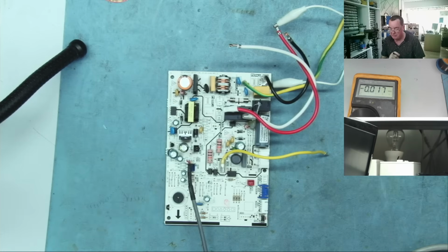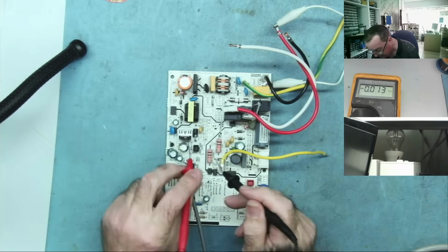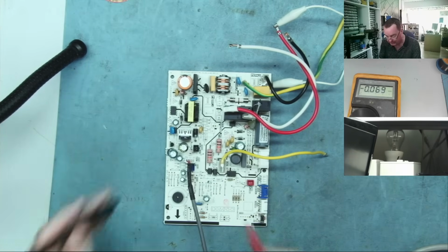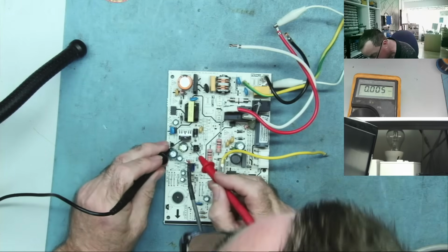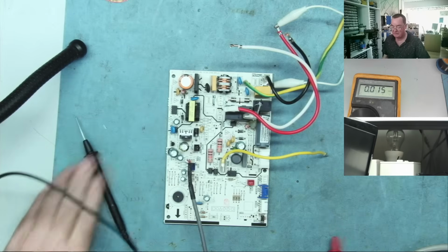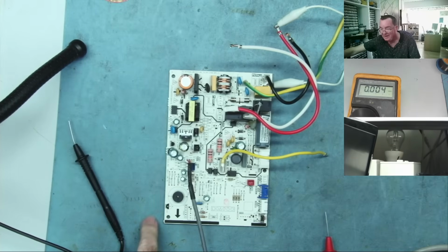Then, I know this is a 7805. So if I measure between the centre pin and the right hand pin, that's the output of the regulator. And if I see 5 volts here to here, I know the 5 volts is there. And if that's there, everything else is probably okay on the power supply. So let's switch this on and let's watch the light bulb. Well, it didn't. Oh, and the thing bleeped. That made me jump. That was the bleeper on here, yeah? Go again.